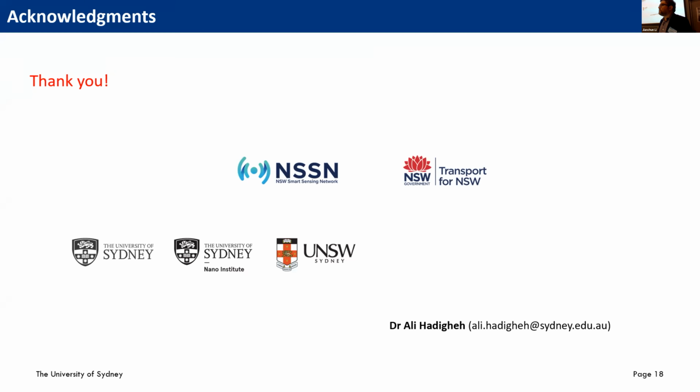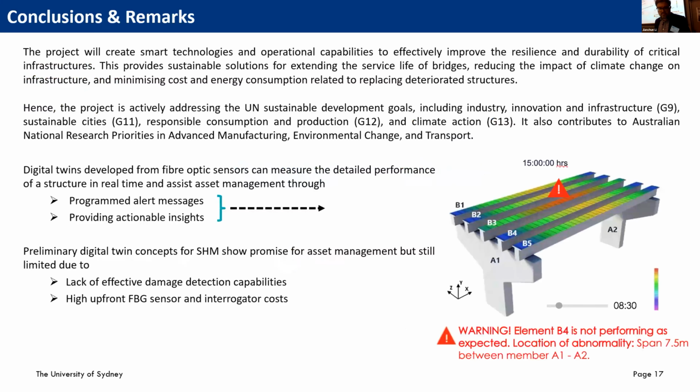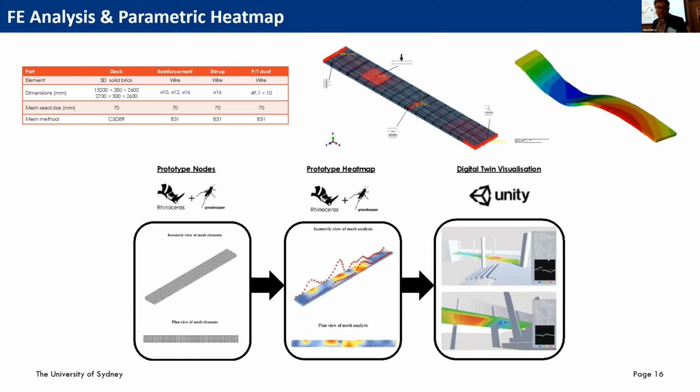The second question was on the platform for the digital twin. I think we use the very normal Grasshopper and Rhino system and Unity to create a digital twin model of it. And we developed a Python version for connecting the strain and temperature data, because that project was on a post-tension bridge, and we wanted to investigate the shrinkage of that concrete performance.